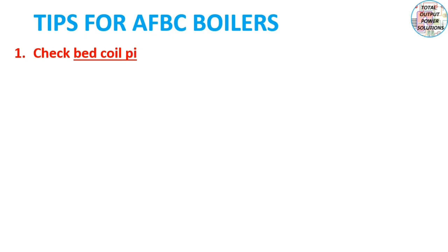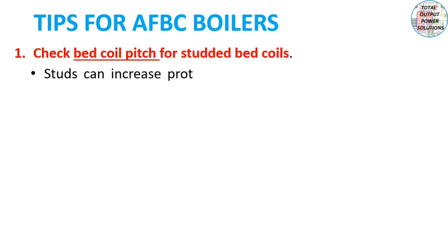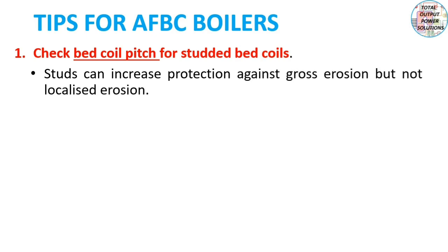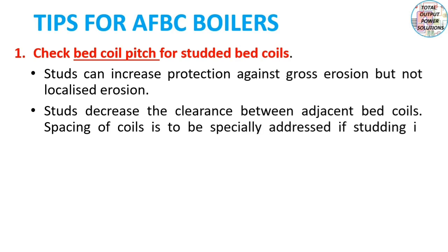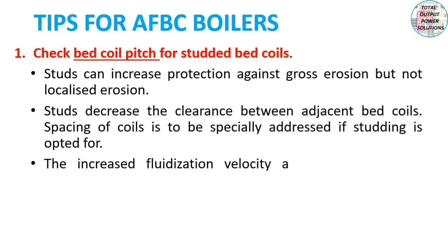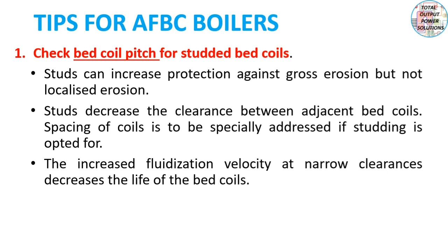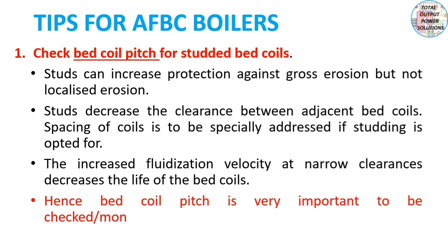The first tip for AFBC boiler bed coils. Check bed coil pitch for studded bed coils. Studs can increase protection against gross erosion but not localized erosion. Studs decrease the clearance between adjacent bed coils. Spacing of coils is to be specially addressed if studding is opted for. The increased fluidization velocity at narrow clearances decreases the life of the bed coils. Hence, bed coil pitch is very important to be checked or monitored, maybe in the shutdown of the boiler.